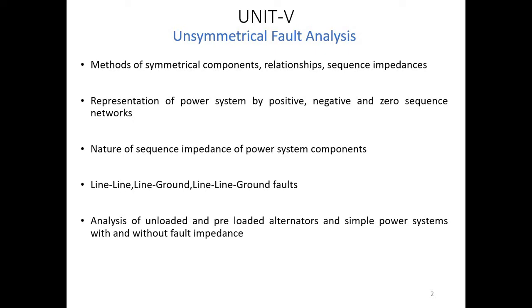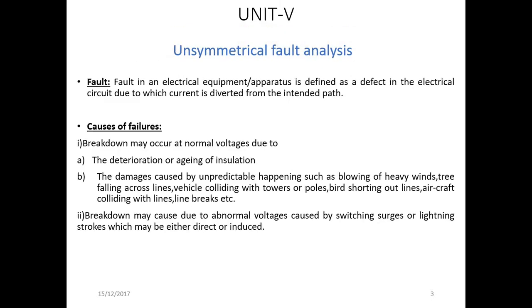During the last lecture, we had discussed what is the meaning of fault, what are the different types of faults present in the power system, what is meant by the symmetrical fault, what is meant by the unsymmetrical fault, and we had started with the method of symmetrical component. So we'll revise the part which is already covered. We had discussed that a fault is an adverse condition in the power system due to which the current is diverted from its intended path.